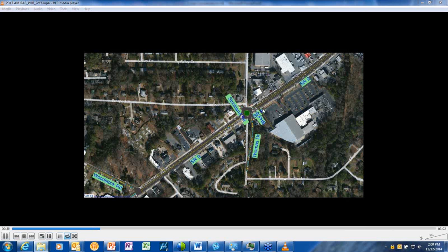We didn't expect that as an outcome. The problem with this is that the background cycle is 120 seconds. And if we only give gaps for pedestrians about every 2 minutes, that might not be acceptable to pedestrians. There's an expectation when you push the button that you get to cross within 20, 30 seconds at the most. If you had to wait 90 seconds for the next gap, pedestrians might just start crossing. So it becomes kind of a policy issue as to whether or not that's a reasonable thing to do.